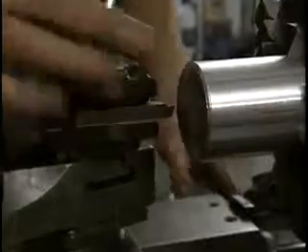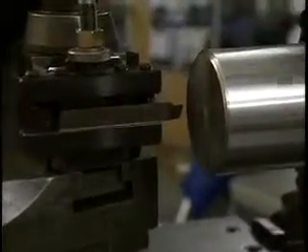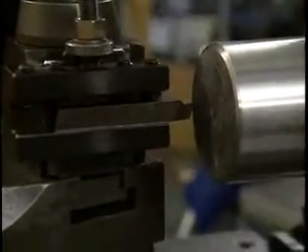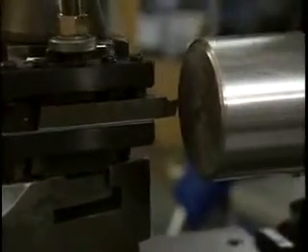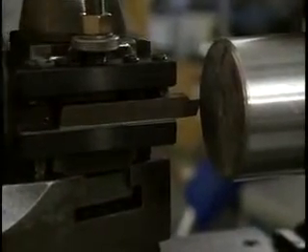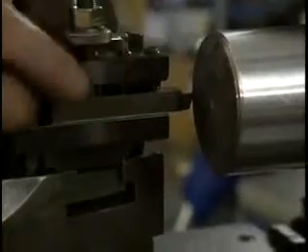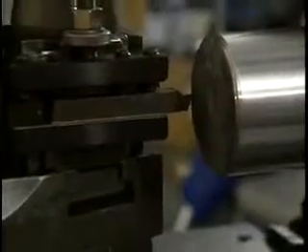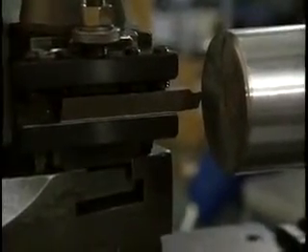Bring the tool in front of the part. Bring the tool close to the part. Turn the chuck just to make sure that nothing is going to collide with anything else. That may be the tool hitting some part of the piece you just put in here because the cut was irregular. It may be parts of the chuck, often the chuck jaws, hitting other parts of the lathe. So always turn the chuck to make sure that there's no interference before turning on the machine.